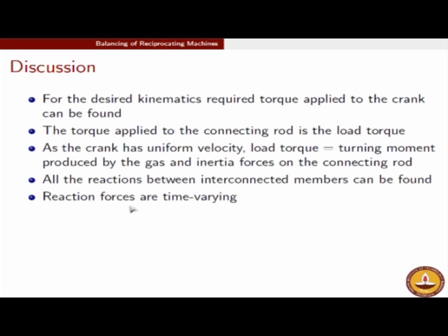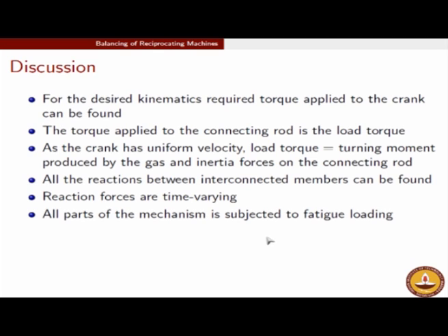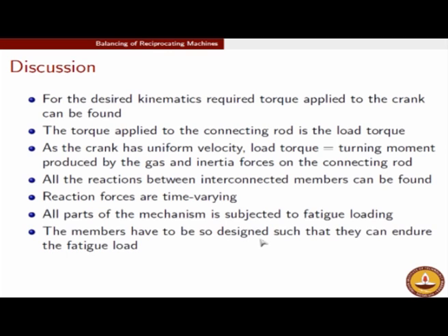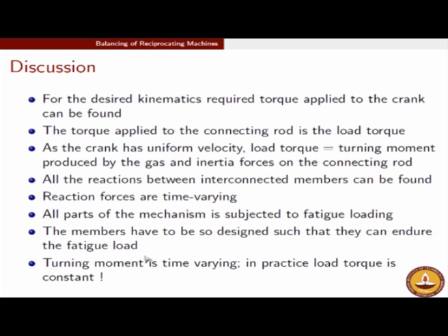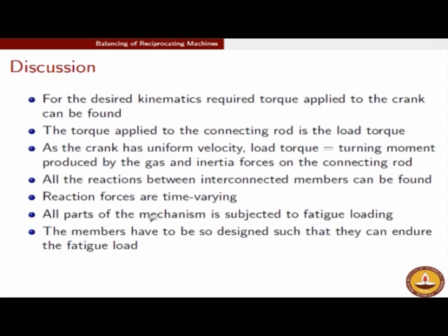As time changes, theta changes, the coefficients of this matrix will change, the coefficients of the right hand side vector will change, and therefore the solution vector will also change. So the reaction forces as well as the m, which is the load torque, will be time varying, and once the reaction forces are time varying, you will see that you are inducing fatigue loading in your members, something we have to be very careful about. The members have to be designed such that they can endure this fatigue load. So at this point, to recapitulate, we have been able to calculate the load torque, which was m, and all these reaction forces.